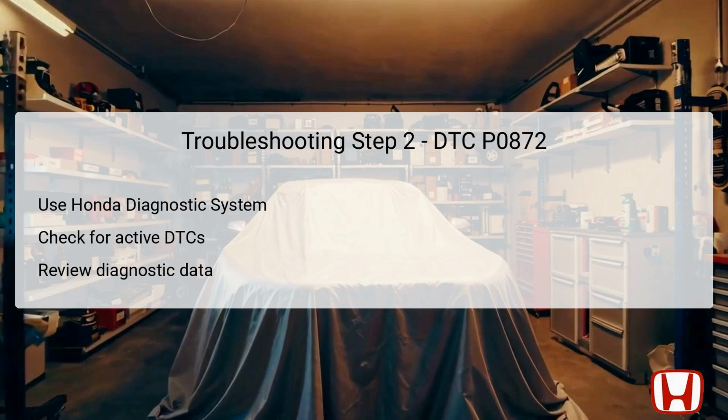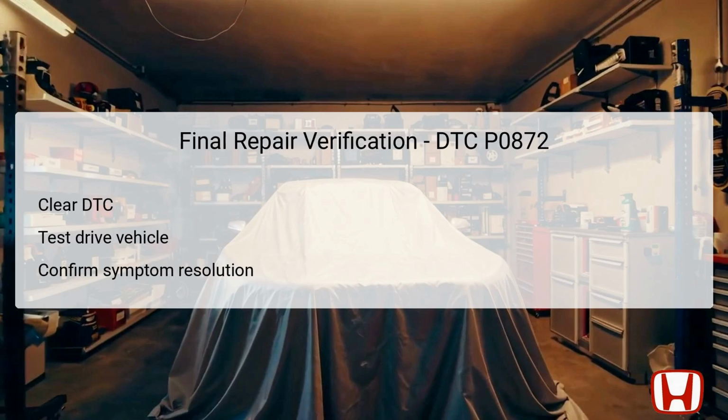Final repairing steps include clearing the stored DTC from the PCM to initiate a fresh diagnostic cycle. After clearing, the vehicle should be test-driven under varying conditions to thoroughly assess whether the initial symptoms and engine warning lights reappear. This ensures that the previous issues related to the fluid pressure switch and transmission operation have been resolved.